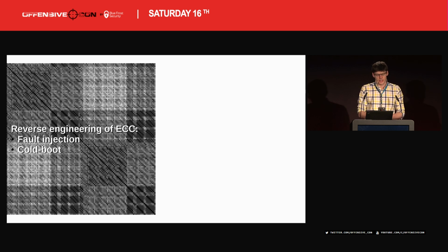This is a 128 by 128 pixel image, and every pixel represents the Hamming distance between ECC values obtained by asserting that position in the data stream. That's why you have the same ECC on the main diagonal.